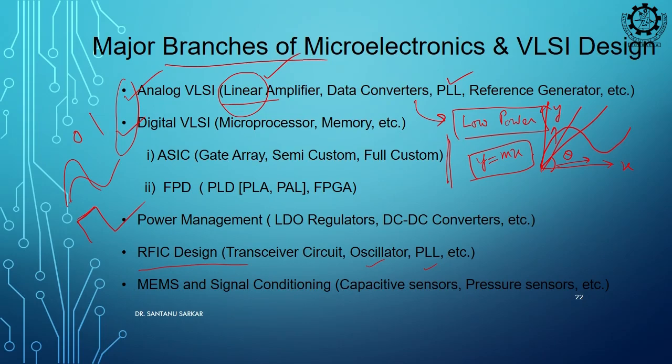We are fabricating a mechanical structure in silicon, for example a comb-like structure for a capacitive accelerometer. So, it is possible to fabricate them in silicon and reduce the size, so that we can use them side by side with the integrated circuit, right.